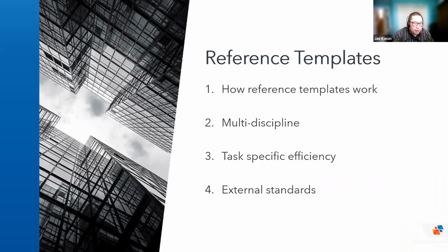So, how reference templates work. Basically, you have a base template, and you have all these other sub-templates that you can reference in. Each sub-template, you can either load or unload. It's basically going to work like loading and unloading XREFs. The reason for this setup is to create specific templates for specific disciplines and tasks to keep things as efficient as possible.